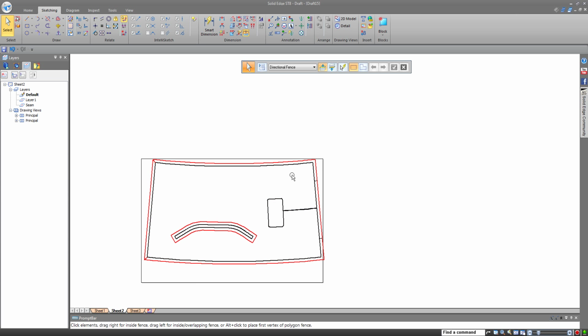Alright, so that is multi-body design. That is using flat pattern to generate profiles from all kinds of shapes. I haven't seen a shape they have not been able to flatten. Without maybe a little tweaking here and there, we could probably get a flat pattern. So very useful tool, again, for people who are doing heater type jackets and or insulation jackets for parts.